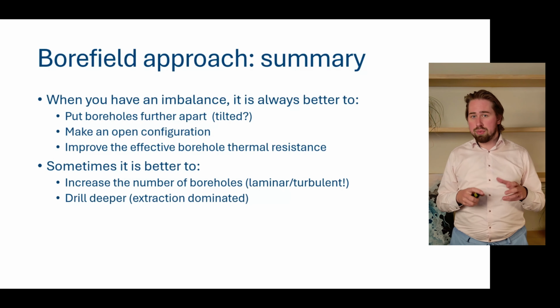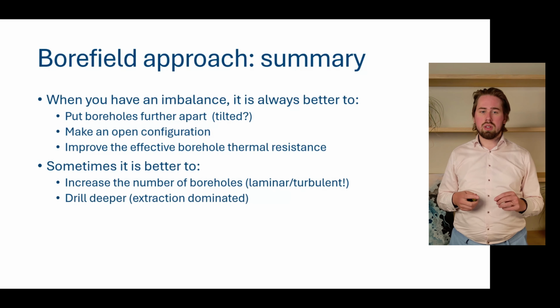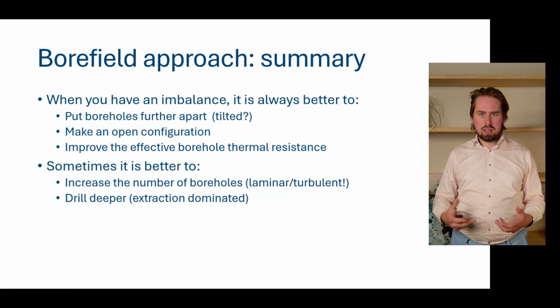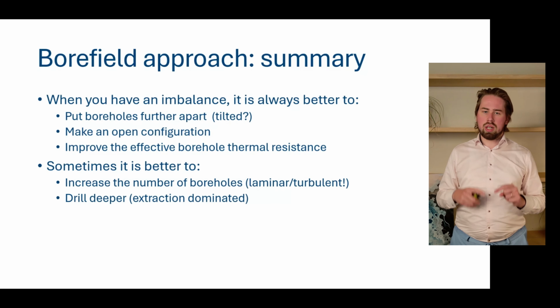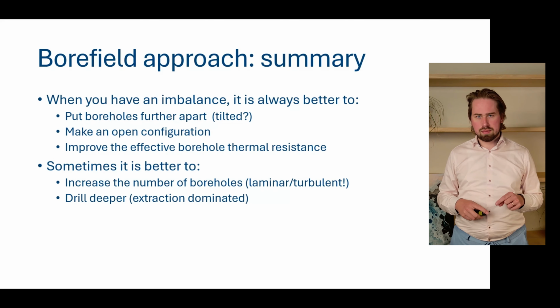On the other hand, we have things that are sometimes useful, namely to increase the number of boreholes, where laminar versus turbulent is very important. Keep that in mind, that you're not just adding boreholes and switching over to a laminar flow rate, because then chances are you're adding boreholes to just compensate for the worse effective borehole thermal resistance. And also drilling deeper is very efficient, but only when we're extraction dominated.